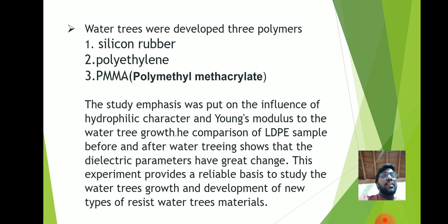Now, the study emphasis was put on the influence of the hydrophilic character and Young's modulus on the water tree growth, and the comparison of LDPE. LDPE means low density polyethylene. The comparison of LDPE samples before and after water treatment shows that the dielectric parameters have great change.